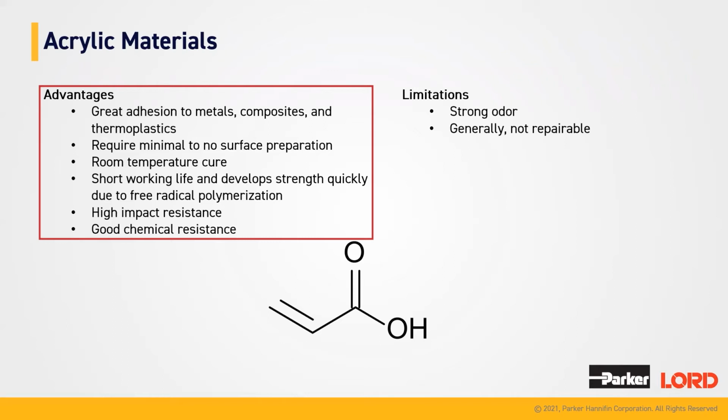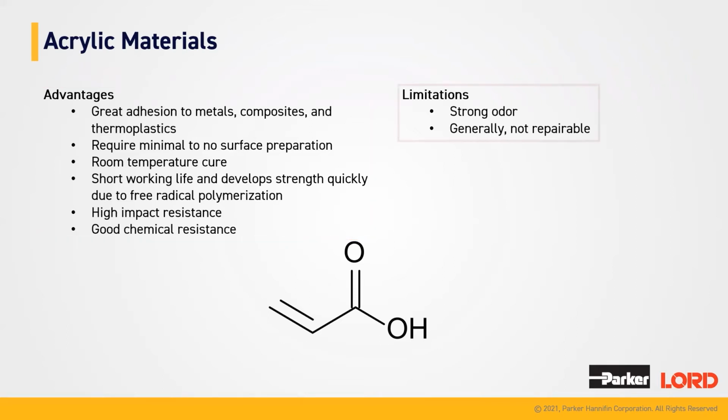They're also very chemically resistant, as well as they offer high impact resistance. Some of the limitations are that they do not smell very good, so they do have a strong odor, that acrylate smell, and generally they are not repairable. Now, it's also worth noting that even though they're not repairable in their typical sense, if the cured acrylic products are paired with our lock release product, they can be repaired, and that lock release can be used to help rework acrylic chemistries that have already been cured.